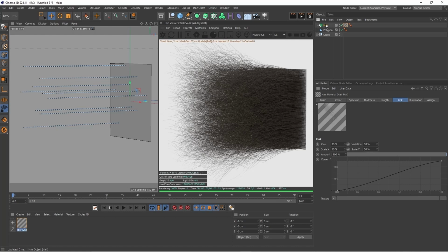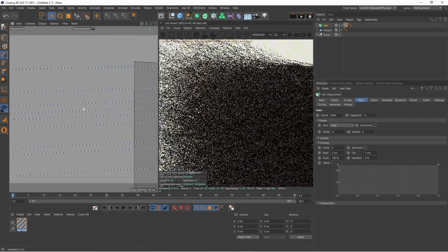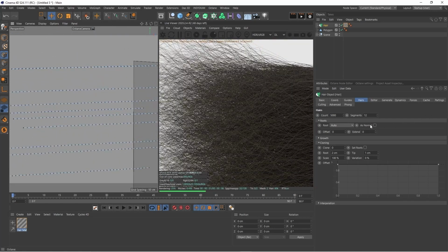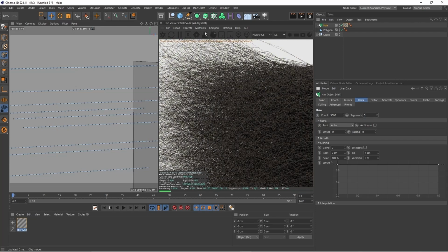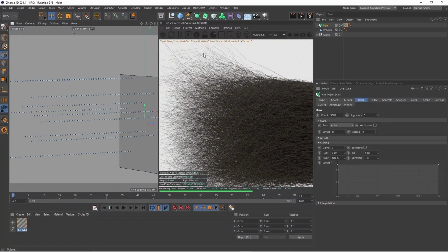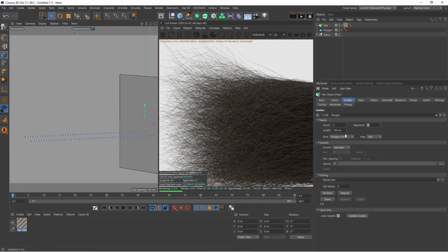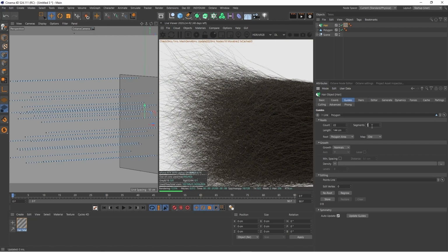Now we're going to be working with things that are directly impacted by the segments of the hairs. So I'm going to zoom in a little bit on this nasty hair, and let's increase the segments. You can see right here there's a kink. Actually, let's lower it first, and we'll be able to see it a little bit better. We zoom out, see all these kinks, and I'm going to try something here real quickly. Whoops, that's not what I meant to do. We'll undo that. Stay at 22. Take these hair segments to 5.